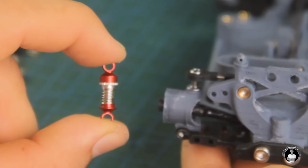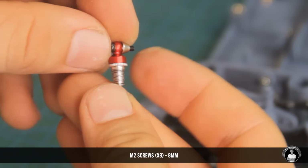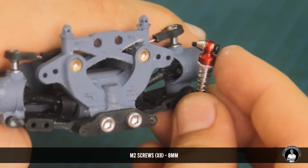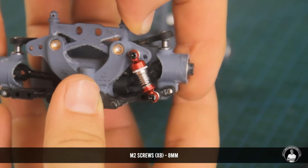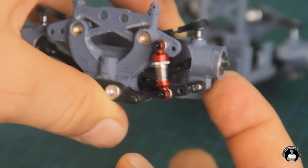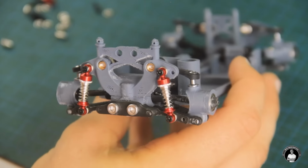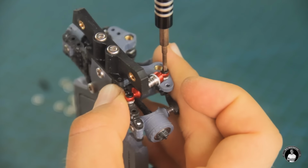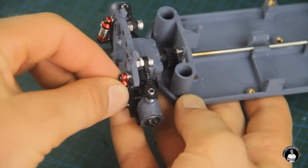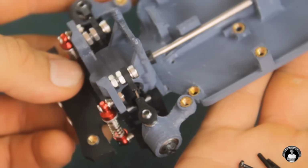For the shock absorbers, we're using 4 of these tiny 26mm 1/28 scale RC car shocks, which take these included spacers and bolts, then get secured to the chassis onto either of the 2 hole pairs in each spot, attaching the lower swing arms to the upper chassis arms. For the shocks to stay well secured, I recommend using longer bolts with nuts.